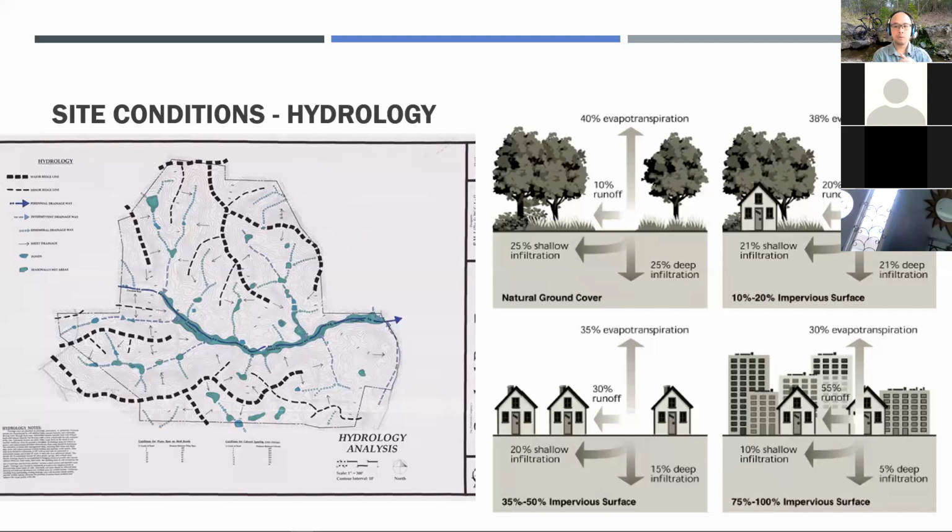The primary paths of groundwater flow and the locations of groundwater discharge to the surface are also important, particularly in more rural locations. Subsurface geologic characterizations may include the analysis of aquifer permeability, thickness, and discontinuities. Maps of groundwater and local geological conditions are particularly important in land use planning, of course, especially for rural areas without access to municipal water service. These site data can help determine potential sources of potable groundwater.